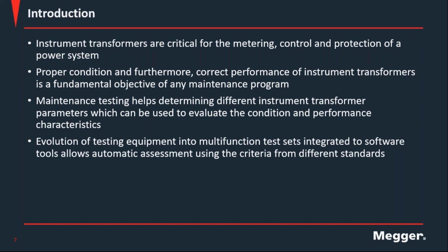This assessment needs, as I was mentioning, results from all the testing, but then it needs some calculations. These assessments were not common when you tested instrument transformers, because performing that assessment required calculations that were not easy in the field, or you didn't have all the test results because the instrumentation out there was not at the level to get all the results and all the accuracy and be capable of performing everything.